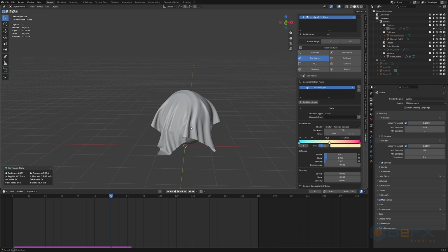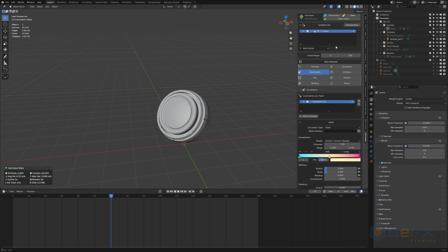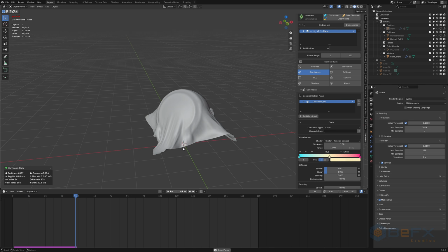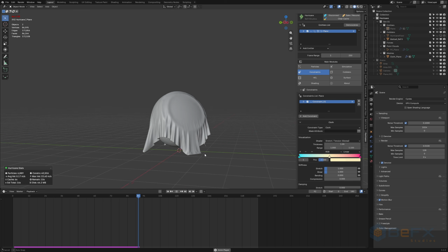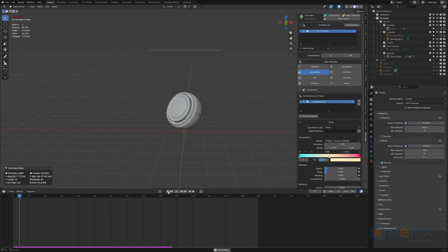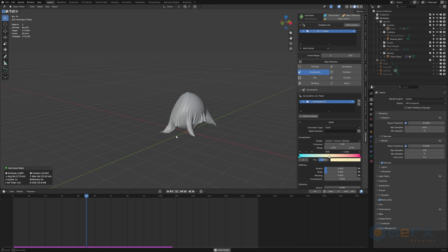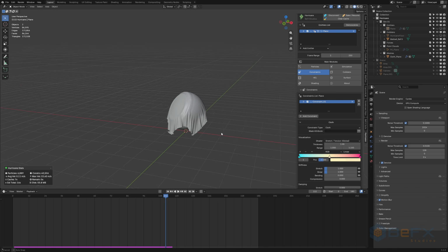Stretch creates links along the main edges of the mesh to resist elongation. Shear adds diagonal connections across quad faces to resist angular distortion. And bending links more distant vertices across adjacent faces to control fold stiffness and bending resistance. Meanwhile, compression governs the response when vertices are pushed closer than their original rest length, preventing the fabric from collapsing or wrinkling chaotically.